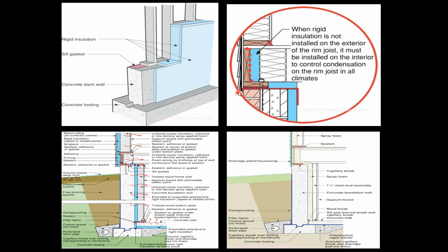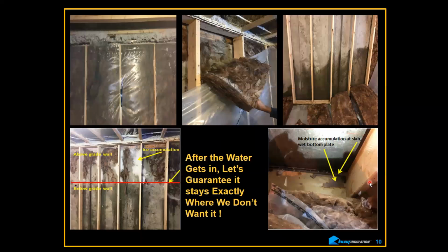Again, another sealant on the top of everything. We're trying to control moisture and air. That's the most critical thing. This is a foam system in here. You're certainly welcome to use that as long as it's installed correctly. That's the problem.